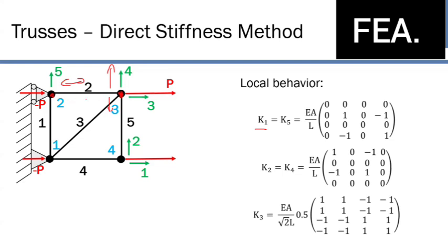My stiffness in the member, because it's a straight truss, is going to be any displacement left or right, up or down in each one. If you imagine it as crushing the truss or stretching it, what that affects in terms of force. So moving this truss up or down, that's not going to cause it to really crush or expand. So as a result, we're not going to get any correlation in the two direction here. Now, if the other node perpendicular to this moves in the positive direction, this one will have to exert an equal and opposite force to restrict that motion. So we get a -1 right here. Okay, does that make sense?